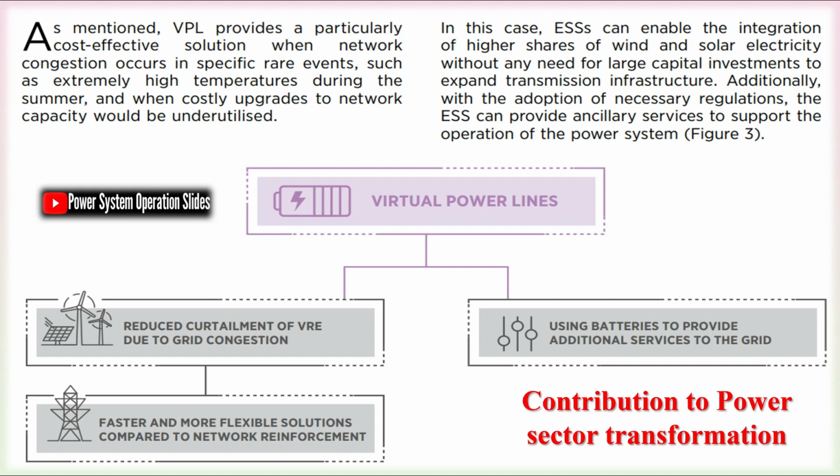Market and regulatory integration: define how redispatch costs, BESS compensation, and curtailment are settled, and obtain regulatory approvals if required. Monitoring and continuous improvement: evaluate KPIs such as congestion hours reduced, MWh shifted, reliability metrics, and tune controllers and update models.